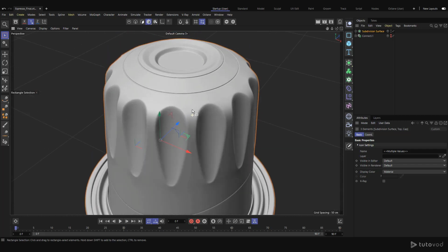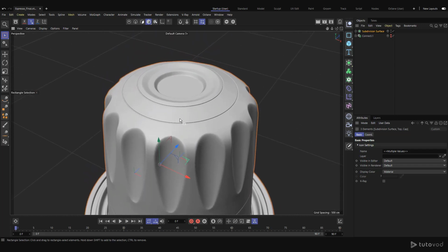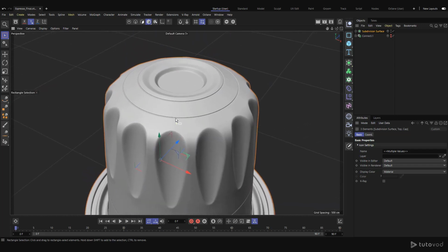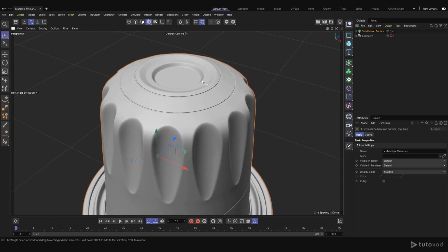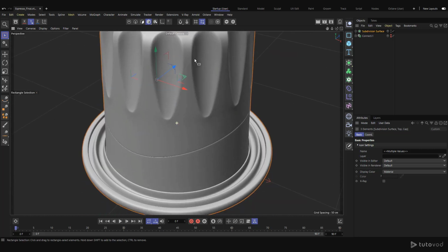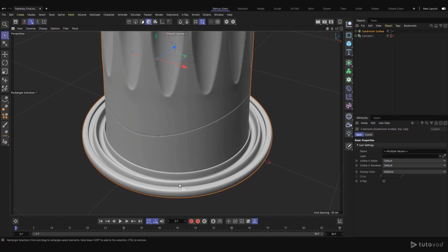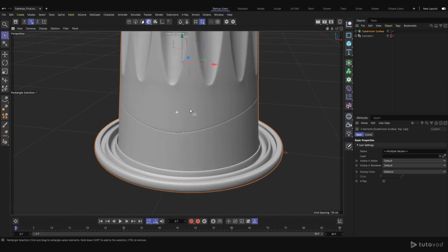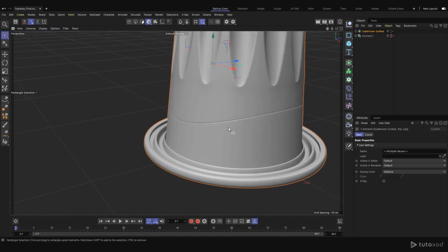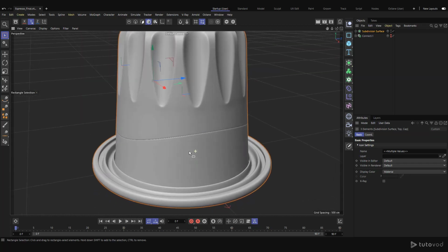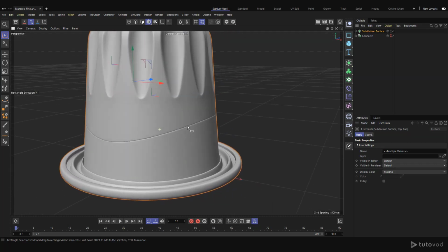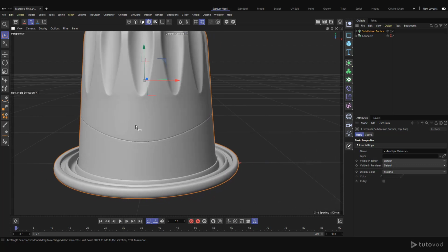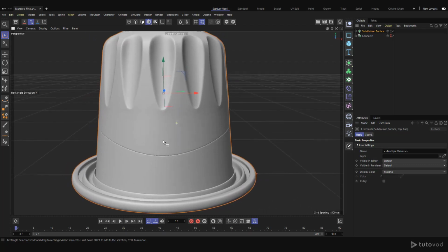and to get the circular shape we have here we need to use a deformer such as a blend. And after that, to model this top shape we need to use a series of extrusions, and we are going to do the same thing here on the bottom. And to get this cut on our model we need to use a spline combined with some tools to get this shape. I will show you everything in the next lesson.